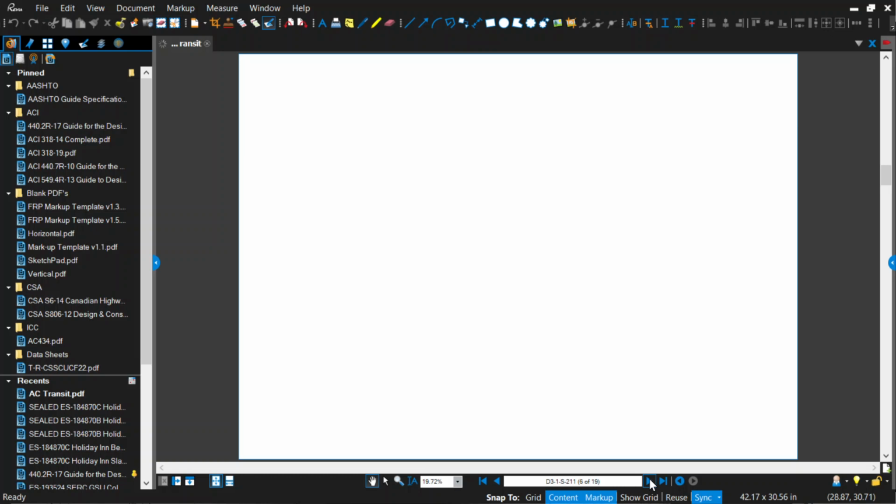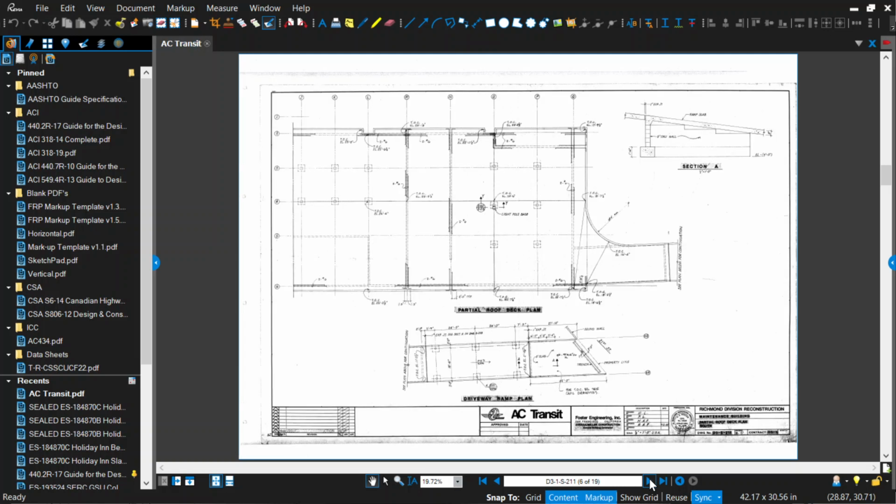Yeah, it has to be at the midpoint. If you're not stressing right at the middle of the slab, then you'll impart a moment. It'll want to spin. So if it went up to the top, then you would have cracking on the bottom. Then you may blow out. I mean, you're putting in almost 27,000 pounds of force on a tendon. So if you're not in the middle, it might also just rip right out the top of the slab.